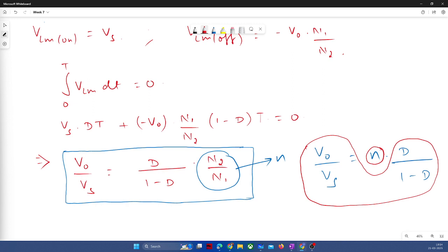Then the whole CCM and DCM is possible. I think it should be possible. It should not be any issue of using CCM or DCM. As you mentioned, you were not able to see whether the converter was CCM or DCM. Generally, manufacturers do not disclose whether it is DCM or CCM, because it is of no use to us as a consumer. But for a designer, it is very much essential, because if it is CCM, then the load variation is very much absorbed and the duty cycle is not going to vary very much.